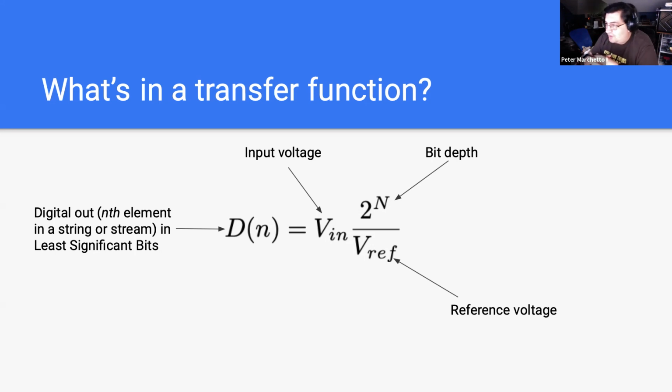We'll come back to that in a minute. So if we divide that by the reference voltage that we're comparing this to, which in our case is usually 2.048 volts, then we know how many individual bits, how many least significant bits we're counting for a given voltage.